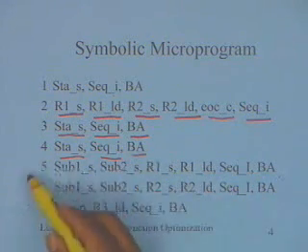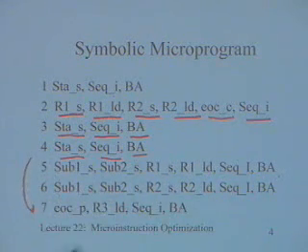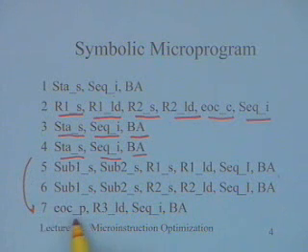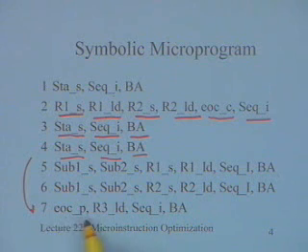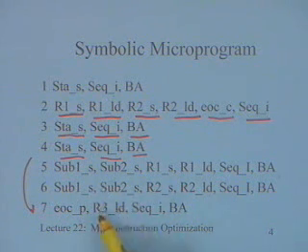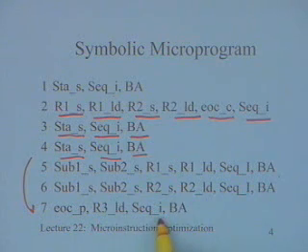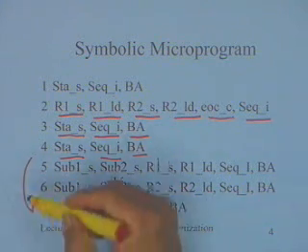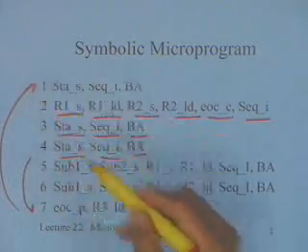Finally, once I jump out from here, if you consider the control flow, I am going to come out here and here I am saying end of computation. This particular thing has to be preset. Now the computation is complete. R3 has to be loaded. It will get the value from the register R1. Sequencer instruction is unconditional jump and branch address, and I will go back to this.